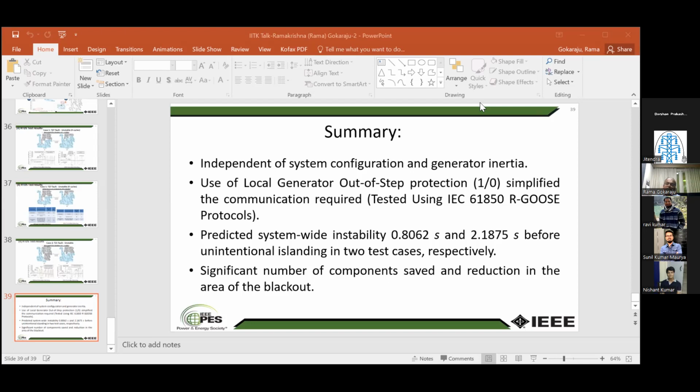Yes, sir. This reminds me of the SIPS schemes and the remedial action schemes. 90% of those schemes are done as planning, in the planning department. The planning department has those simulation models. They will create those events at different portions of the network, and beforehand they already know that if some events happen on those portions at different places on the network, how the system is going to split. So they already have that information available for the operators.